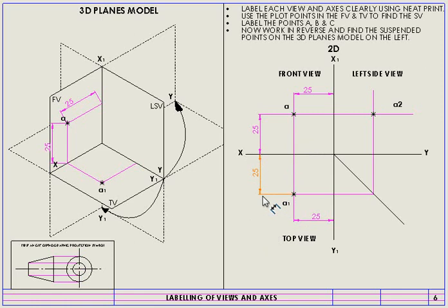If I look at my 3D or my isometric model, the 3D planes model, my XY axis runs all along these 2 lines over here for now. Okay, so if I go away from this XY axis, this direction, 25 millimeters, that will give me this point. Remember, I have already a projection 25 millimeters away. So if I simply project it down and 30 degrees across from that intersecting point over there on the axis, I will have a natural 25 millimeters away from here.